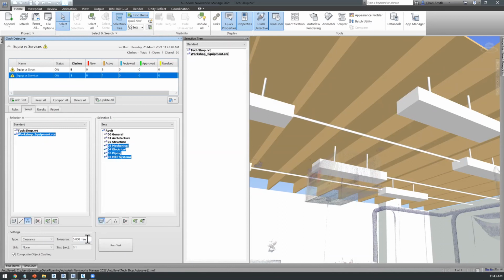And lastly, when we do this test, we've got to provide a larger than usual tolerance, because the gaps between the points could very well be 5 mils apart. They might be 10 mils apart. So we need to provide a tolerance so that we can pick up the gaps between the points within those scan files.